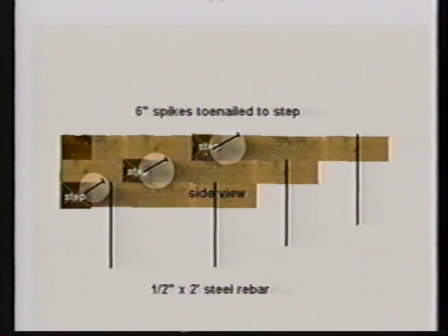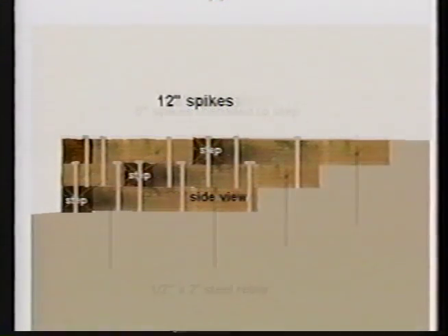These timbers should be anchored on native soil. Install them by first toenailing them to the base timber. Next, anchor them to the compacted native soil with rebar.